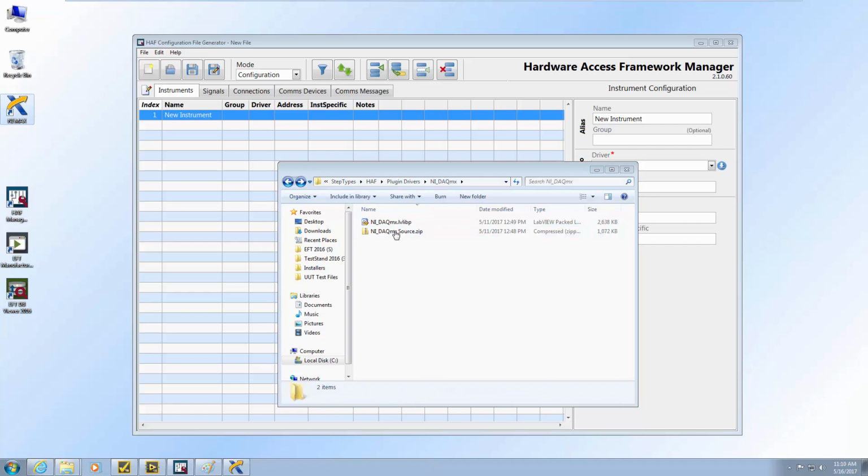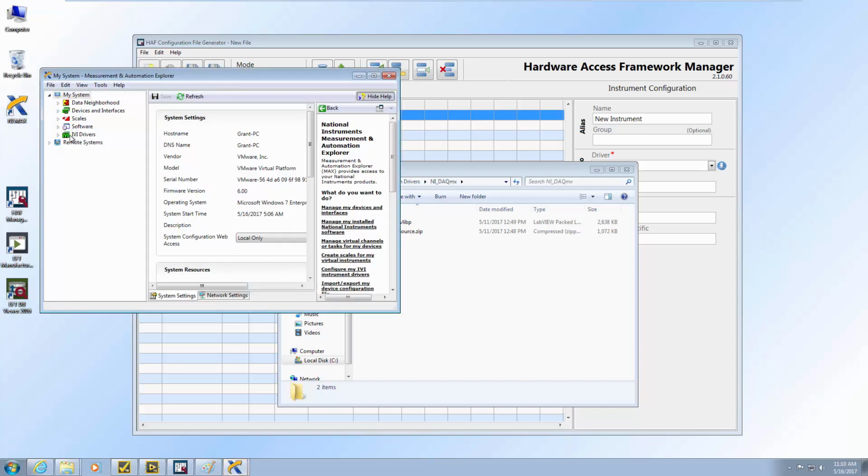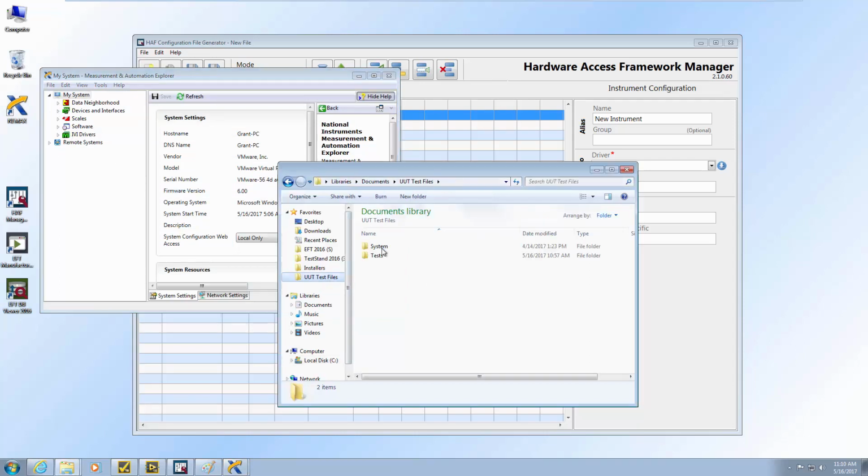As part of our development, it's helpful if we first have some instrumentation. So let's create some simulated instruments in NI Measurement and Automation Explorer, or NI MAX. While it's not required to have instrumentation installed, it makes the process of developing the channel configuration file easier. For this demo, I'm going to use the shipping example that ships with the EFT module for TestStand.